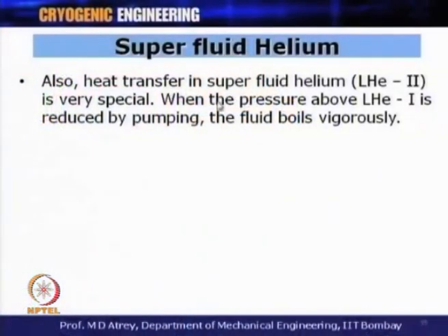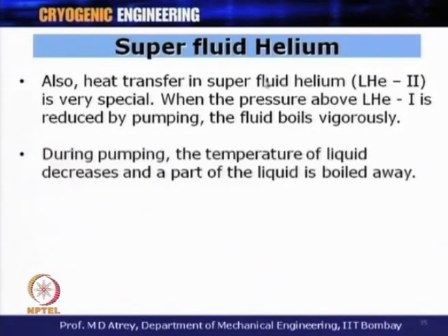If we talk about heat transfer, we just talked about viscosity. The heat transfer in superfluid helium, that is liquid helium 2, is very, very special. When the pressure above liquid helium 1 is reduced by pumping, the fluid boils vigorously. So, if I remove the pressure, the boiling of liquid will happen. During pumping, the temperature of the liquid starts decreasing. So, I have some liquid helium 1 and I remove the pressure over it.